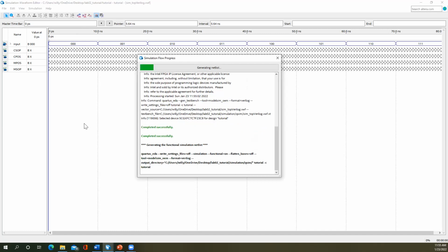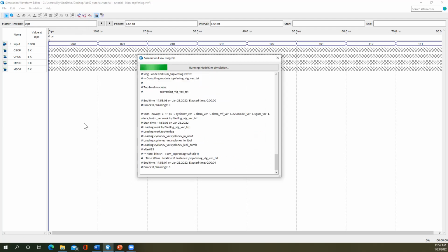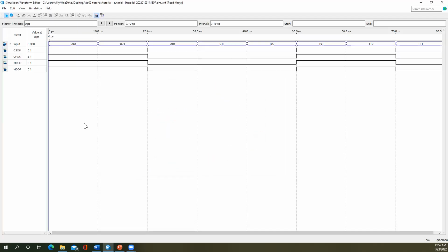And of course, we're going to expect all four outputs to look alike. Of course, it's possible that I've made an error. Oh, good, I did not. So all four of our circuits, right, they're all equivalent forms of the same function. They should all produce the same outputs. They're all producing ones for inputs of 0, 1, 5, and 6, and outputs of 0 for 2, 3, 4, and 7. Right. So we know then our Verilog implementation of all of those circuits is functionally correct.